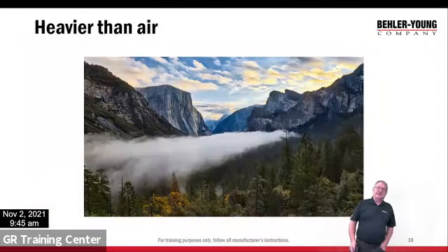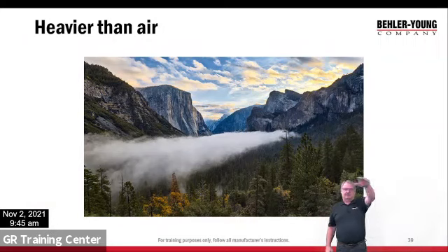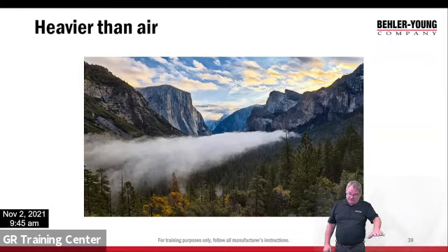So if you were to look in a basement, again, this is fog, but this is a good depiction. So imagine you're in a basement. Imagine this little valley is the basement of a house, and you have a leak, a propane leak. And that propane is heavier than air, so it's going to settle to the floor, and it's going to do what we call puddle. So we're going to accumulate this propane down at the floor, or gasoline down at the floor.